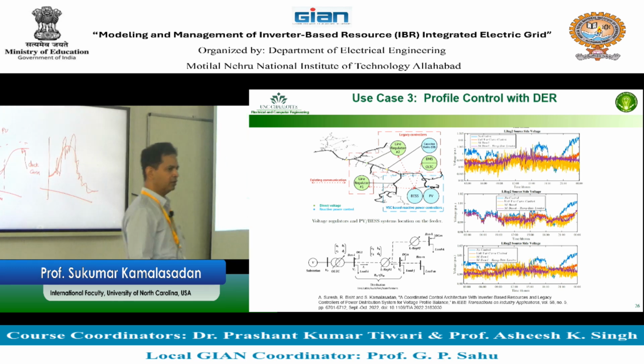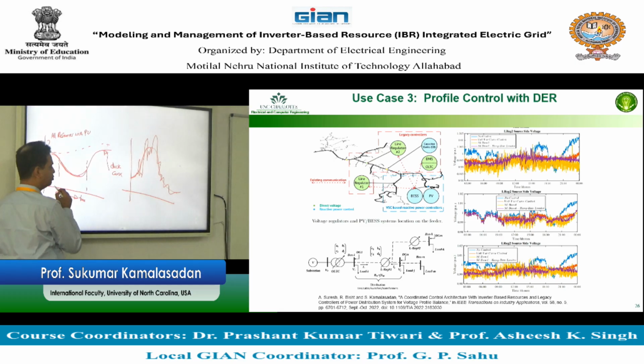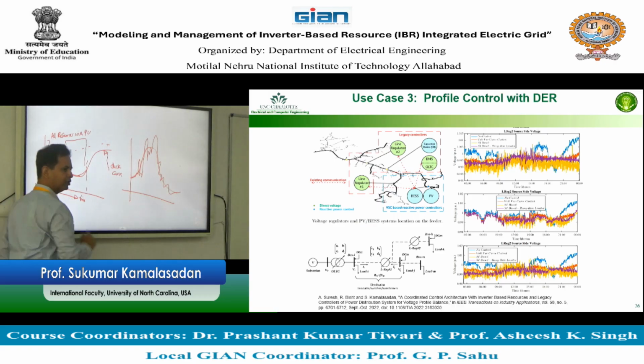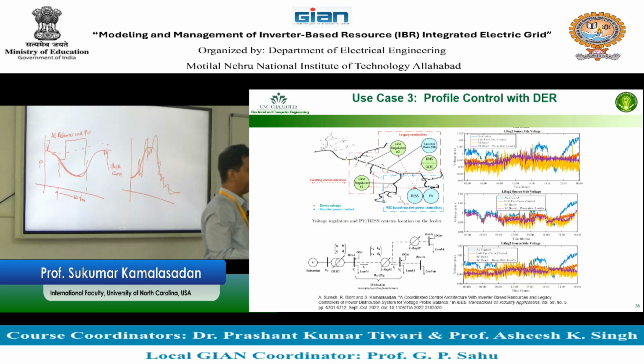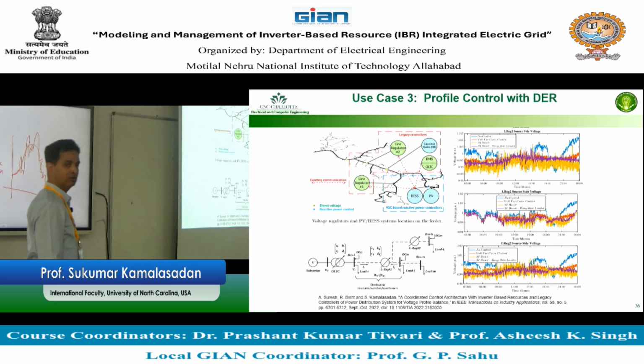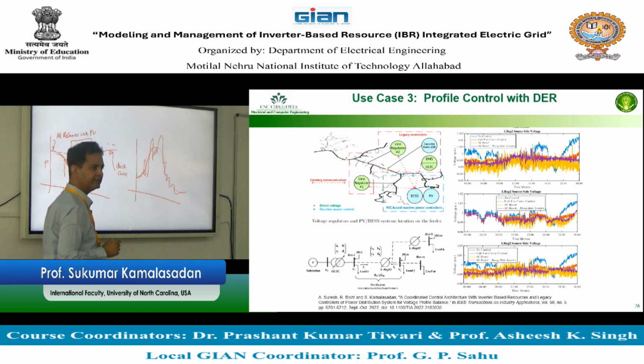Okay. Now, if you have this and you are actually trying to lift a load and there is a load change that happens at this point, you will need to work against normal operation to satisfy the load. On top of that, with the PV, you are dipping, going down because of that load, right? So what do you have to do? You have to have somebody who actually ramps really fast at this point. If you don't ramp really fast, then you're out.